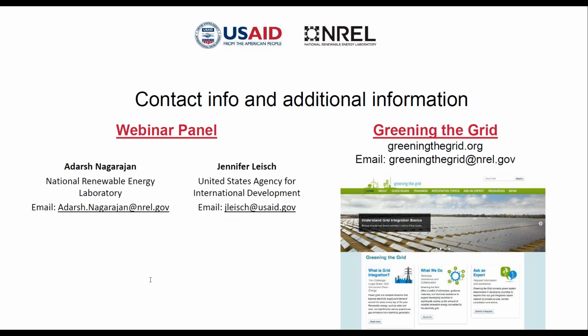That's great. You talked quite a bit about DERs, and a question has come in on whether there are similar efforts at the transmission level for wind and solar, or if these grid codes can be applied in the same way, or are there major differences that people should be looking out for? That's a good question. As I brought up previously, P2800.1 is currently ongoing work in progress. It's at a preliminary stage at this point, but that's one standard that's being worked upon to address the questions related to interconnection at transmission level.